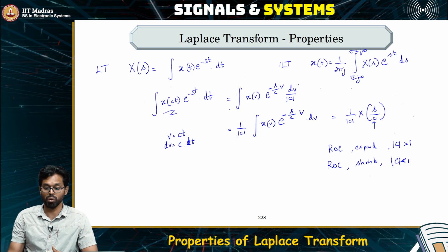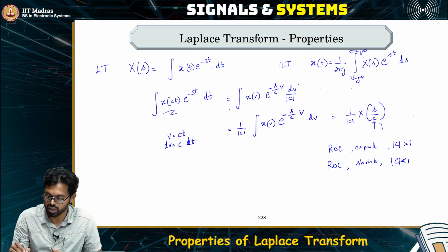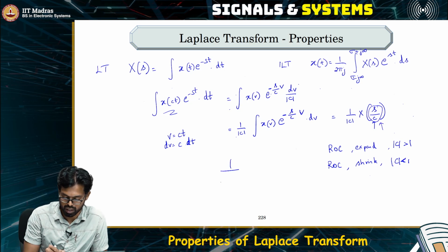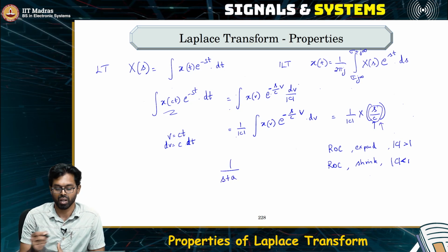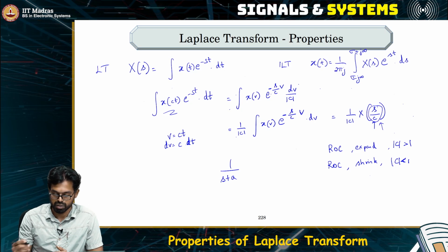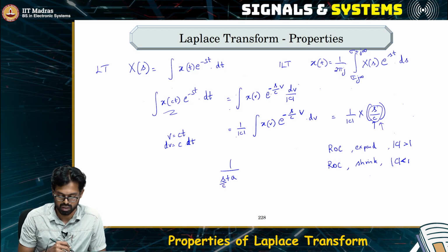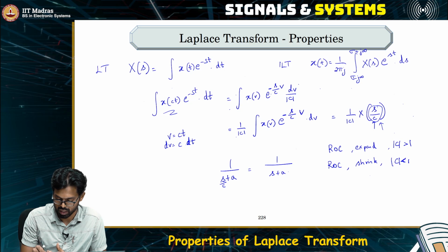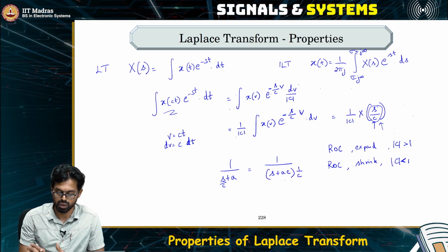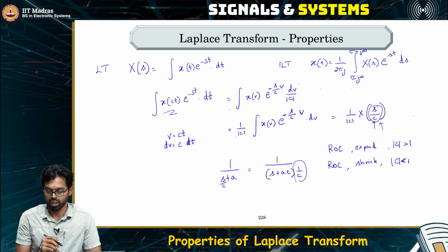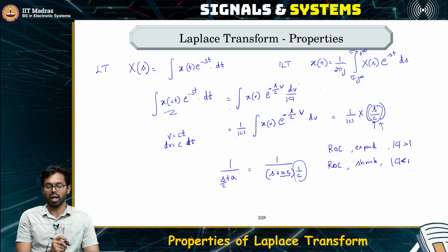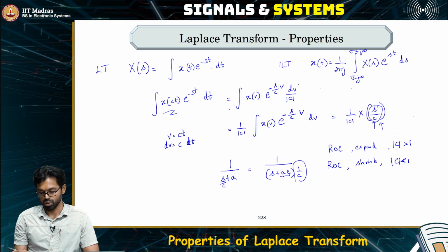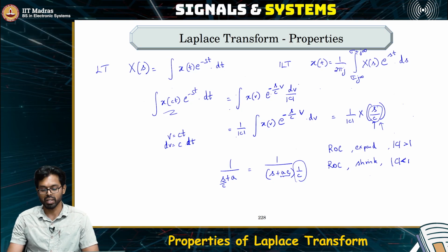But what happens to the poles and zeros? So as you can observe from here, all we are doing is just replacing S with S by c. In other words, if we had a pole which looked like this, now after this time domain scaling, we have S by c here, which is now equal to 1 by S plus a c whole times 1 by c. Now this becomes a constant, so we can ignore that. So the poles and zeros just get multiplied with this constant c. So the poles and zeros also now change, they simply get scaled by the same amount.